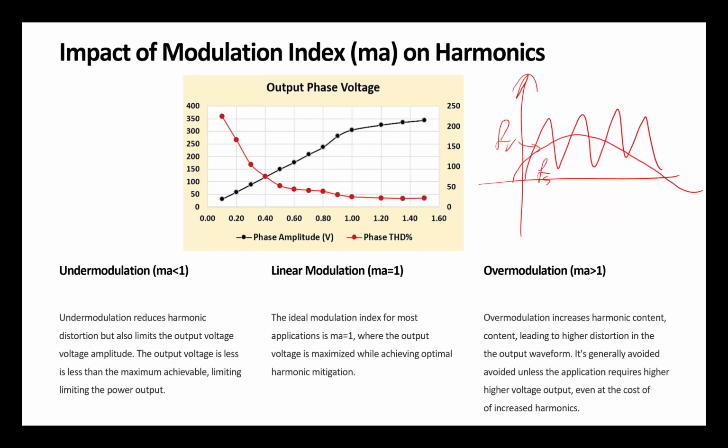There is going to be some variation and errors. There could be errors or malfunctions in our system that result in a reference voltage going higher than 1 volt, or per unit wise. Meaning now the modulation index is higher than 1.